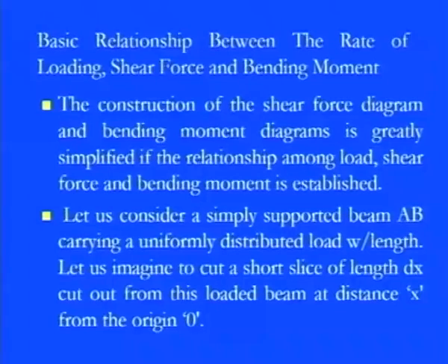And let us imagine cutting a short slice. We just want to focus on what the overall impact is. So we cut out a short portion of length dx from the loaded part at a distance x from the origin. We start from a point which is the origin, and from distance x we cut the portion, and we want to analyze, under this rate of loading, what kind of shear force and what kind of bending moment there is.